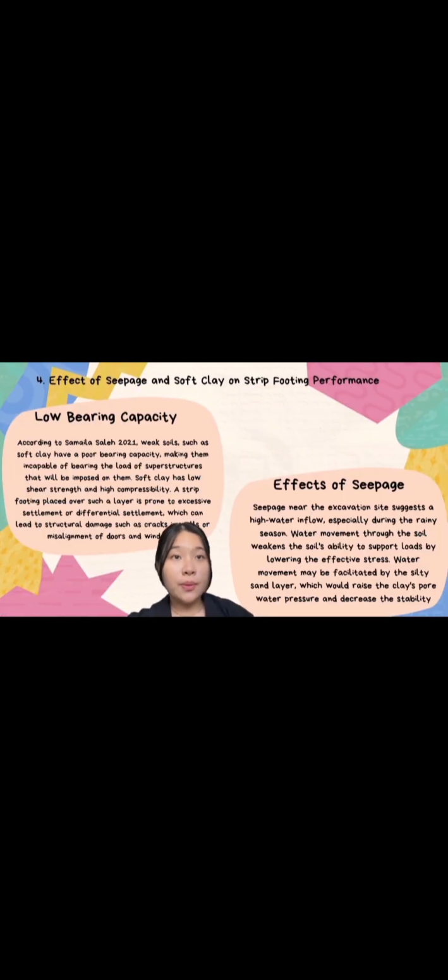The next one is the effect of seepage and soft clay on strip footing performance. As we know, soft clay has low bearing capacity, and according to Samaila Saleh 2021, weak soils such as soft clay have a poor bearing capacity, making them incapable of bearing the load of superstructures imposed on them. So when a strip footing is placed over such a layer, it is prone to excessive settlement or differential settlement, which can lead to structural damage such as cracks in walls or misalignment of doors and windows.